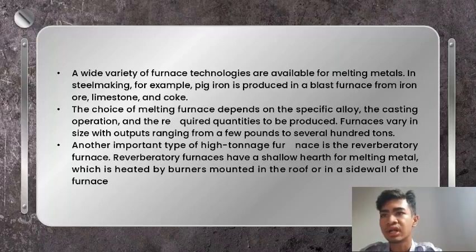Alternate layers of scrap metal and coke are charged into the top of the cupola, and the scrap metal is heated to the melting temperature by direct contact with the upward flow of the hot gas. The molten metal droplets are collected in the inner portion of the cupola known as the well.